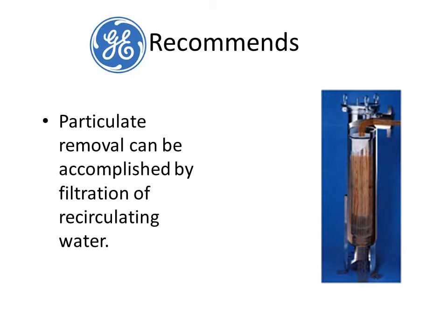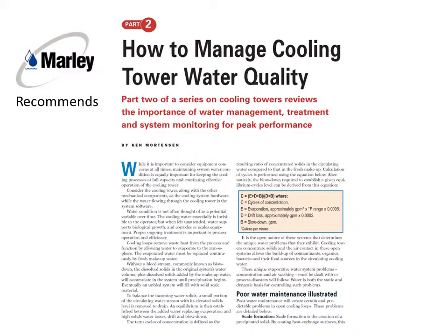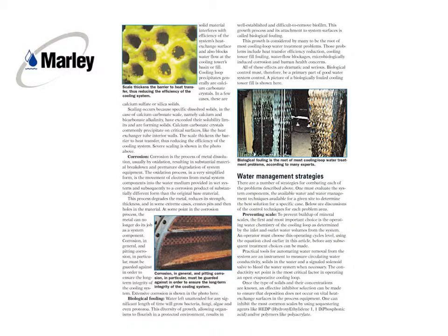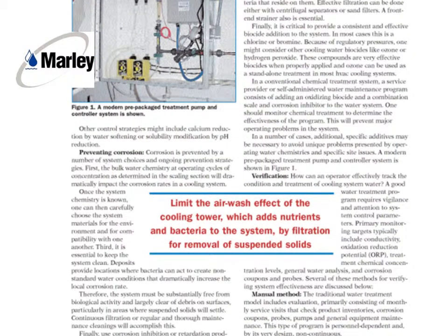GE recommends the removal of fouling with filtration. Nalco also recommends removing or reducing the volume of fouling by filtering and cleaning the tower basin. Marley Cooling Tower provided an excellent review on how to manage cooling tower water quality. Note where they put the necessity for filtration in bright red letters.